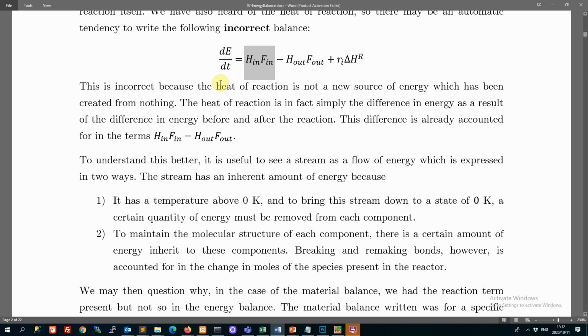So most of the time, that is energy flowing into the system, even if this temperature is lower than the temperature in the reactor. Still, that's energy that's flowing into the reactor. If you like, you can think of it as an energy momentum that's pushing into the reaction space. And in a similar way, when we have a flow coming out of the reactor, then there's a loss of energy to the space as well. So that's the flow of energy into and out of the space. And then we are starting to say yes, and that fully accounts for the reaction heat as well. So we're trying to unpack that here.